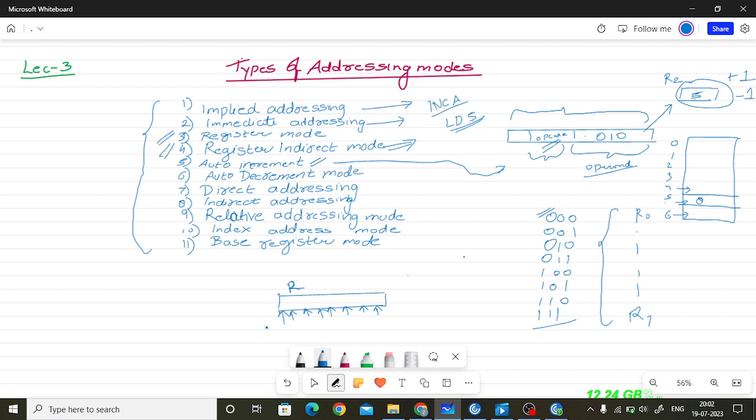So in an 8 bit register, 8 flip flops are connected side by side. If we want to increment, we connect the flip flops in such a way that they act as counters. If we trigger it with a clock, this will act as a counter. If we have stored 5, what is the binary code for 5? 101. So 101 is stored in this.